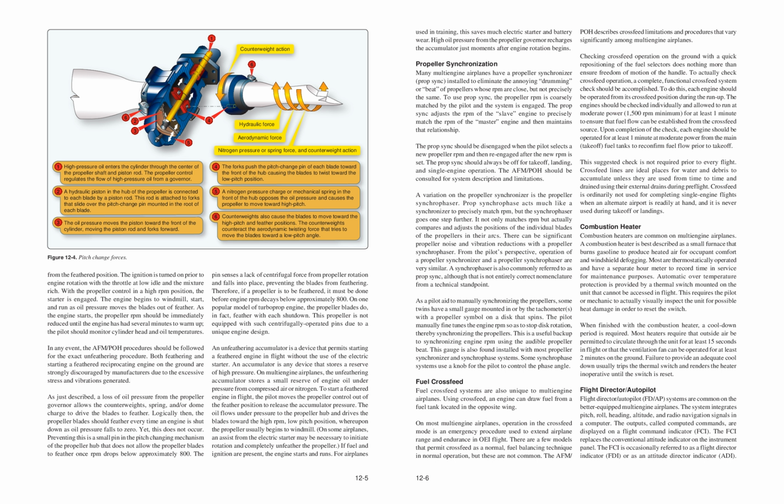From the feathered position, the ignition is turned on prior to engine rotation with the throttle at low idle and the mixture rich. With the propeller control in a high RPM position, the starter is engaged.